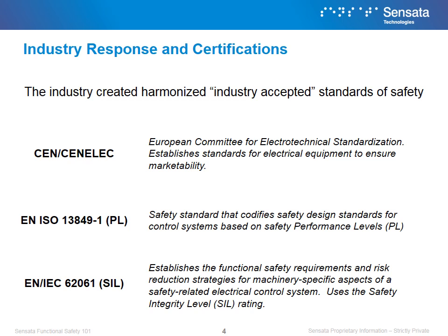EN/IEC 62061 is the safety standard that establishes the functional safety requirements and risk reduction strategies for machinery-specific aspects of a safety-related electrical control system. This standard is referred to as SIL or SIL rating.